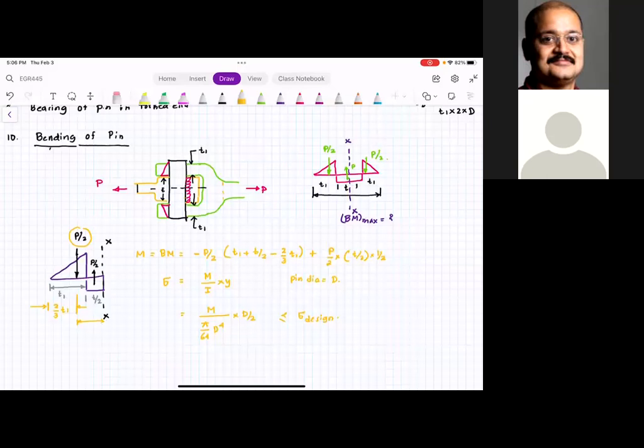The design that we are doing here is purely based on the principles of mechanics of materials. But please understand, the analysis done here is a planar analysis, while the knuckle joint is not a planar geometry. It's a three-dimensional geometry, which means it has curves in all 3 dimensions, so the loading is going to be complex. Based on experimentation, experience and empirical dimensions, they came up with some proportions where the knuckle joint can be easily manufactured. Usually the joint would be manufactured by casting, and then the joint can be machined.